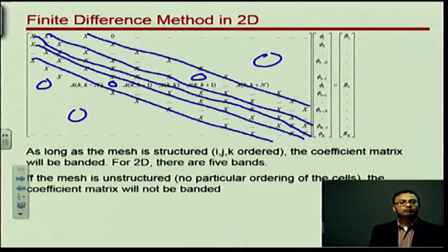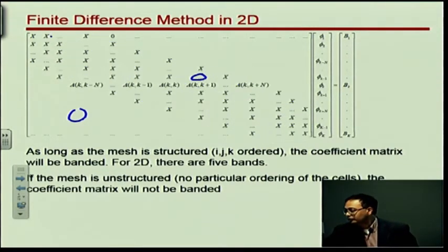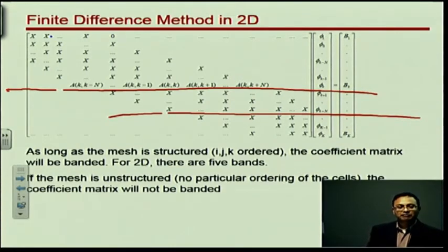For something like a Gauss-Seidel line solver for an unstructured mesh, your stencil would be changing for each node, right? Because some nodes might have 5 neighboring spaces, others might have 9. Yeah, sure. So what that means is that one row may have 5 elements, this row may have 8 elements. It's perfectly okay. Nothing wrong with that. And that's why you don't get a banded system anymore for unstructured mesh. If you have a structured mesh, you can't have 5 for some and 8 for some. By definition, they'll all have the same.